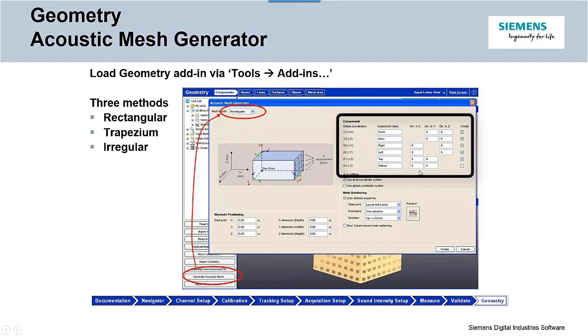Now, if you are using the 9614-1 standard, then you need to define how many points you want to measure on each surface, be it the front, back, right, left, or top. But on the other hand, if you are using the 9614-2 standard, then for the front side, it will be like a one by one grid. So you don't need to break it down into multiple points.